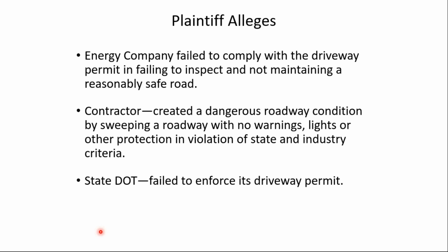The allegation against the contractor was that they created a dangerous condition by sweeping a roadway with equipment that had no warnings or lights or other protection, which of course violates the MUTCD. It also violated this particular state's temporary traffic control manual. And the allegation against the state DOT was that the state failed to enforce its driveway permit.